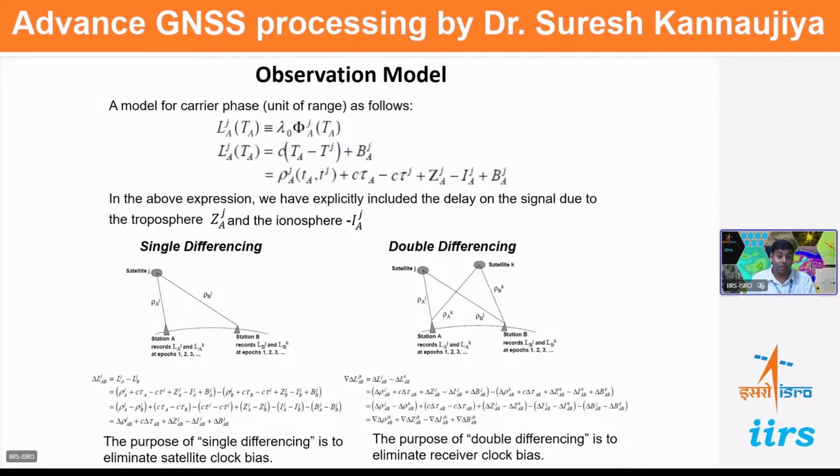From right-handed it becomes left-handed, and when it comes back to the phase center zone, it is not detected, because our antenna is intended to receive only the right-handed polarized wave. This is how we eliminate the multipath to some extent, and the rest we model and eliminate from the error budget of our data.